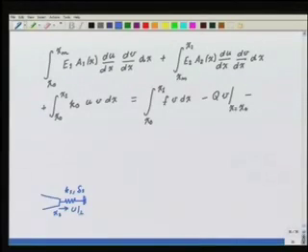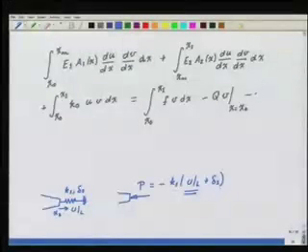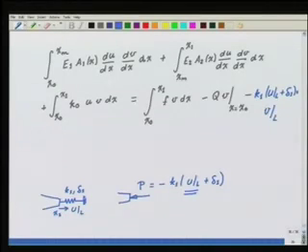So the total compression is delta 1 plus U of L. So the force applied by the spring back on the member is P equal to minus K1 (U at L plus delta 1). Now you see U at L is an unknown. So let me first write it here, minus K1 (U at L plus delta 1) multiplied by V at L.